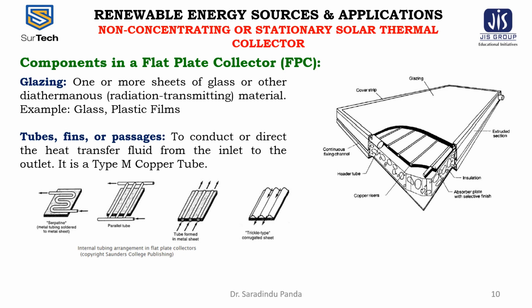Air can be used as the transport fluid in some of the designs of the flat plate collectors. This option is better suited to space heating applications or crop drying. A fan is usually required to facilitate the airflow in the system and efficient heat transport. Certain designs can provide the passive movement of the air due to the thermal buoyancy.